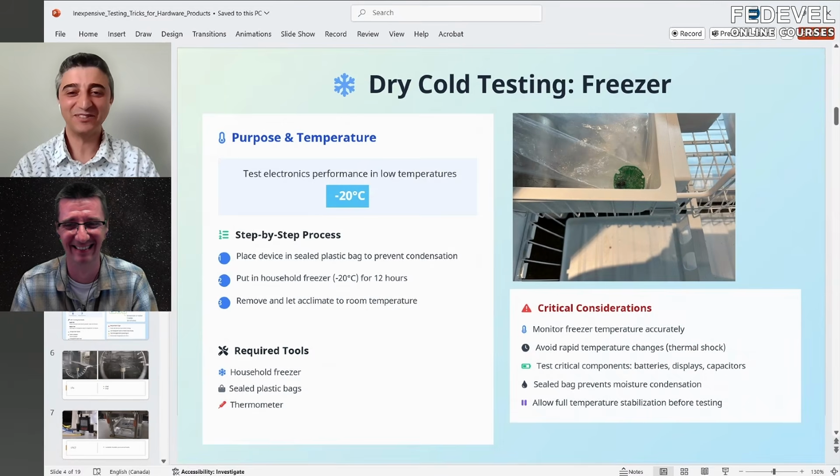Yeah, I agree. So if you use 22, maybe 24 or 26 gauge wires, you can still slide them inside and keep the seal. I think the freezer is one of the funniest and easiest ones. You don't have to turn on anything. It's already working. You just dump things inside and it will work. So really, it's an easy one. I would highly encourage anyone who's doing designs with electronic circuits to do this. Put it even inside a Ziploc bag and drop it inside.